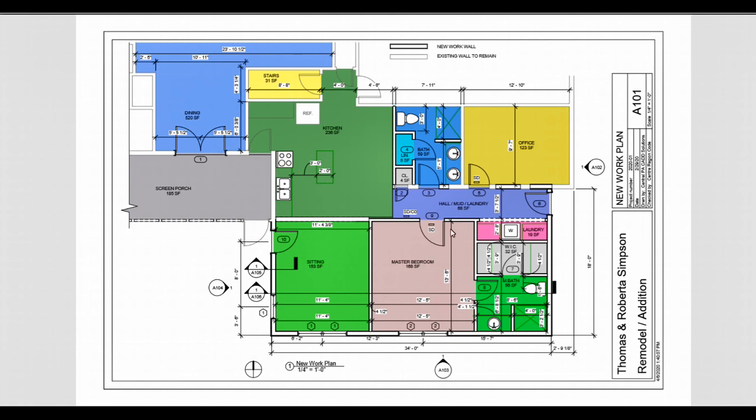All right, so other things to note on the drawings are dimensions. So the dimensions a lot of times can get confusing very quickly. So first thing that I want to look at are the exterior dimensions. I want to make a couple notes of the exterior dimensions. Typically, I have one that shows any offsets within the building. Here's an offset within the building. And I have one that shows all the dimensions for the openings.